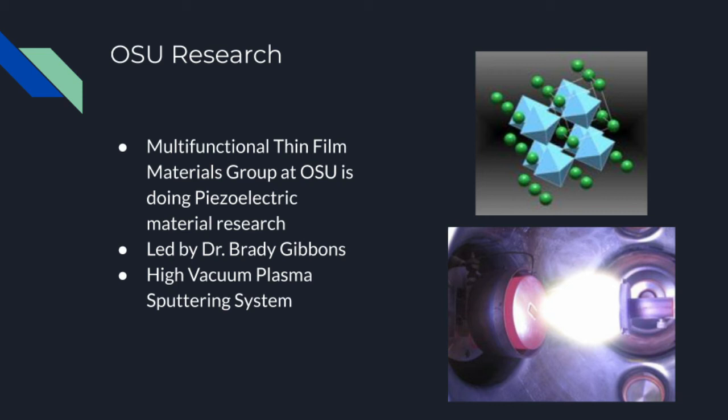The second image here is a view from inside Dr. Brady's custom-designed sputter system. The sputter system is used to apply platinum electrodes to the face of the thin films to be tested for electrical properties. To put it briefly, sputtering is a plasma-based deposition process in which energetic ions are accelerated towards a target. The ions strike the target and atoms are ejected, or sputtered, from the surface. These atoms travel towards the substrate and incorporate into a growing film. In this sputter system's case, argon ions are energized to strike a platinum plate and are ejected onto a holstered thin film. A grate is then placed over these thin films to create the electrode pattern on the surface.